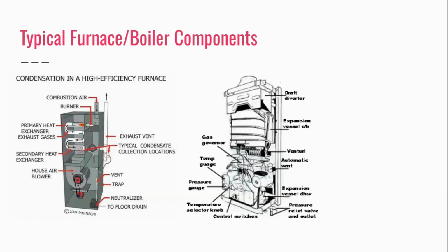That's pretty much it on the furnace. And then we have a gas valve on both. Super important. Gas valves go bad all the time. And typically when they go bad, it's intermittently. They do not fail outright.